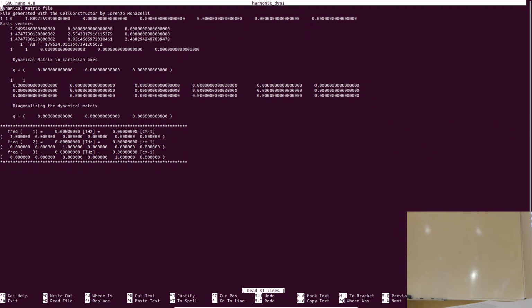It is unnecessary. It is both unnecessary and very bad because then you would need to calculate the second derivative of the primitive with respect to the fourth-order root, and we don't know the analytical formula. So that would be a mess. Actually, I think the code crashes if you do that. So if you are using preconditioning, don't use the fourth root. If you are using the fourth root, don't use preconditioning.